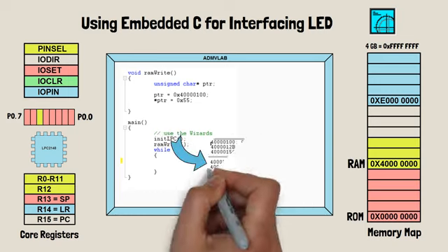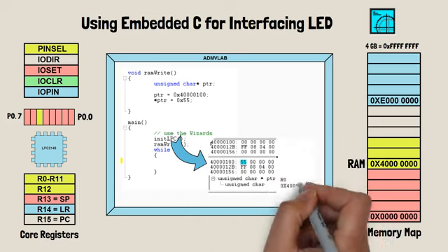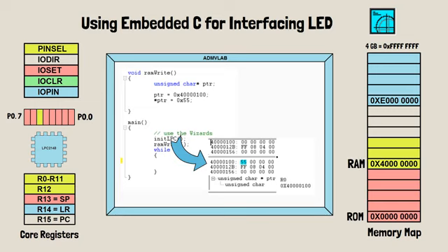We create a character pointer, we point this to a location in RAM, we check the value of RAM. It has a value 0 before stepping, and 55 after we single step our function. This means we can now access any location on the memory map using pointers.